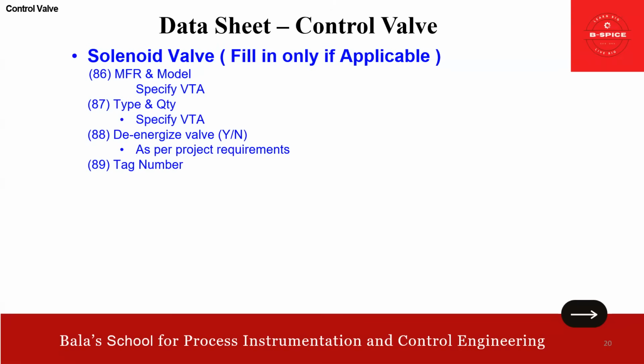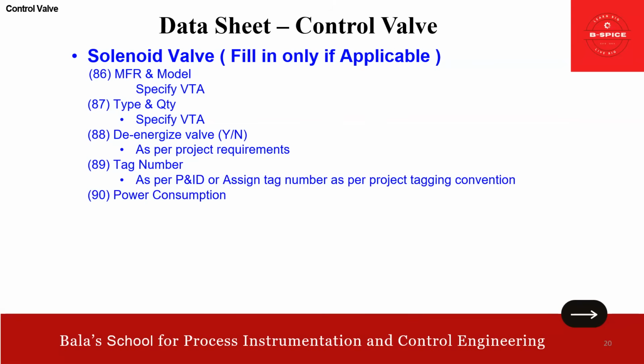So I again repeat, specify valve stroke direction when solenoid is energized. It is recommended normally to adopt the energized circuitry, unless there is a specific requirement like energized to open or close the valve for special applications such as FGS. Anyway, you don't bother much on this. You just put it as yes or no based on the requirement.